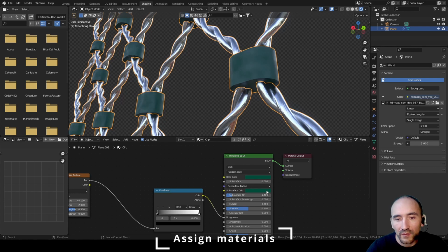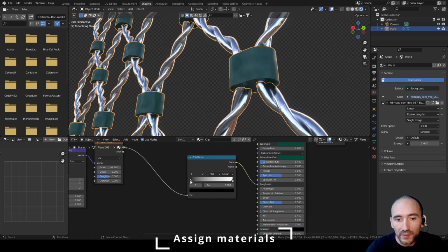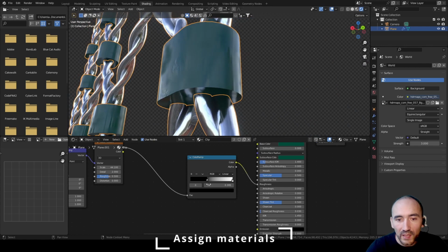This we don't care of this attribute because we have no subsurface scattering, and we can use this color map to get a better result of the roughness, and we can increase this black to dark gray to never get a pure clean plastic or similar material effect.